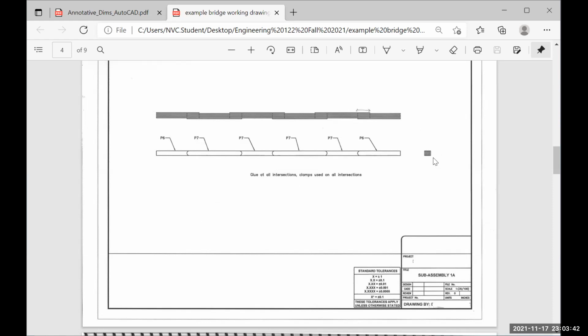They've got their note, right side view, top view. Okay, so we start to see how these are coming together. This is part 6, this is part 7, and how they come together. One piece of information they're missing is the overlap distance right here. And that could have been a note placed in a triangle here, note number 1, all of those sections here, a little triangle with the same note 1, because it looks like it's symmetric. And down in here, note 1 would say overlap by, I'm making this up, 1 centimeter.